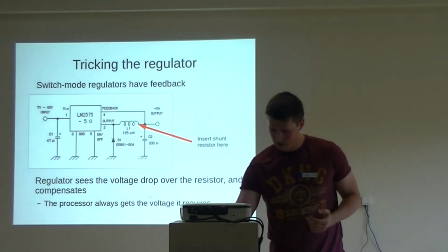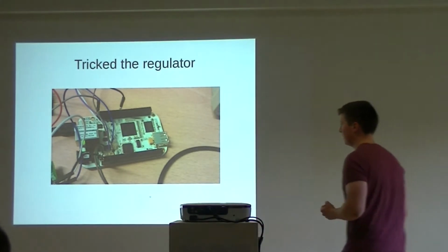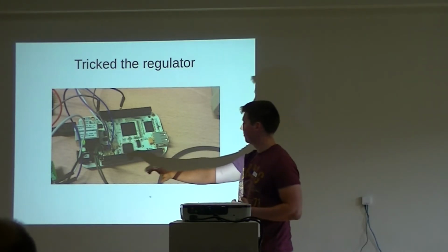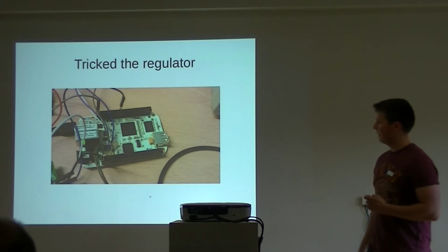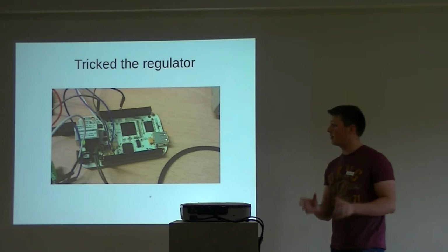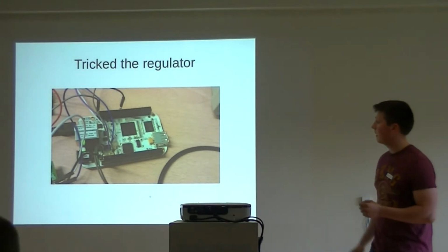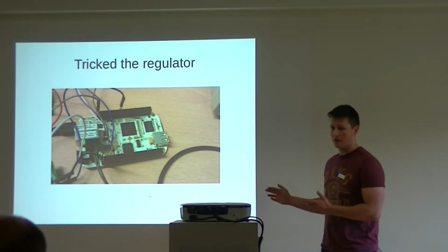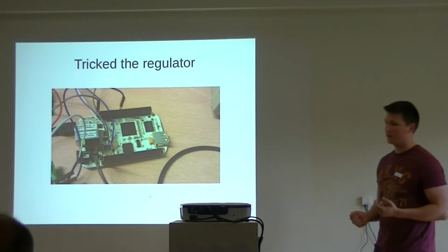So we did this with the Beaglebone. See a horribly hacked apart Beaglebone here, where we've taken off 3 different measurement points and stuck some wires on, and these wires go off to our energy board with an inductor and the shunt resistor on there. So this is quite useful because this allows us to measure the processor's energy consumption, the hardware peripherals, and the memory. So it allows us to break it down into those 3 different categories.